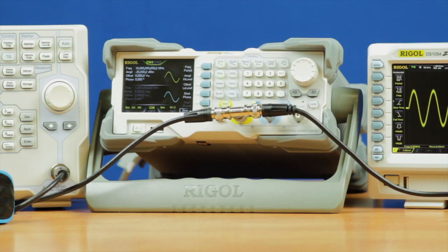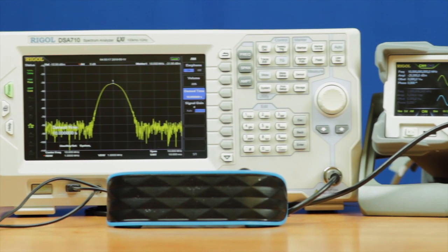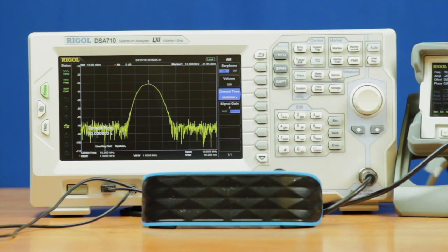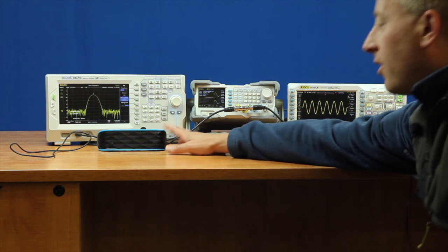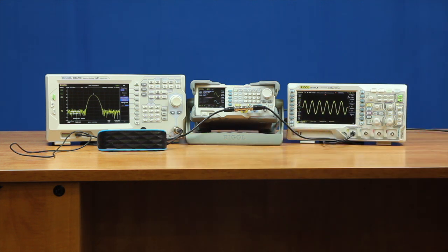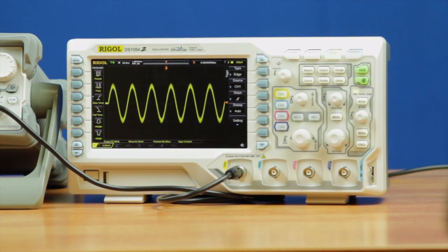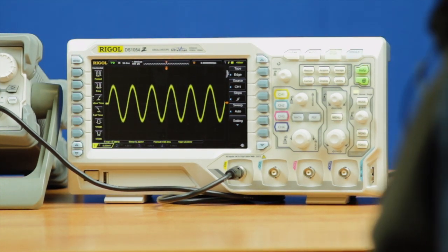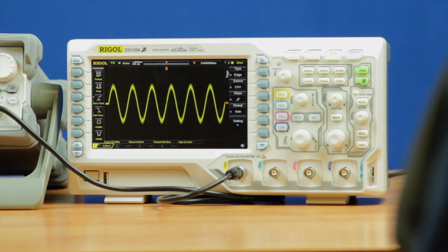So here you can see the generator is modulating that signal, putting it up on the 10 megahertz carrier, and then transmitting it, in this case both to the scope and the spectrum analyzer so we can visualize it. Then the spectrum analyzer is doing the additional work of demodulating the signal into the speaker here where we can hear our music come across. The interesting thing here is we can see in real time the amplitude modulating slightly on the scope, but it's very difficult to fully demodulate it in that sort of time domain view.